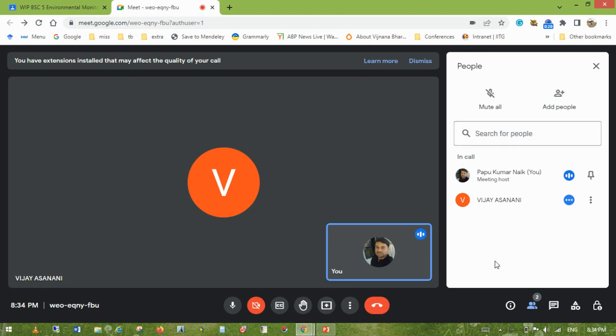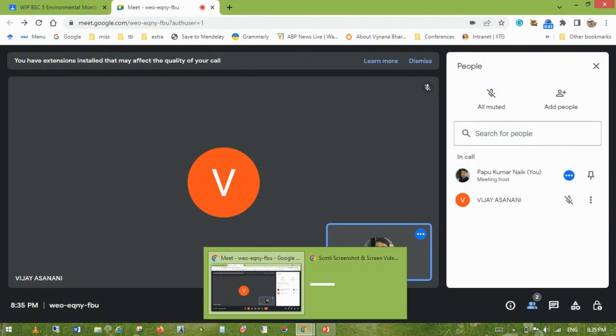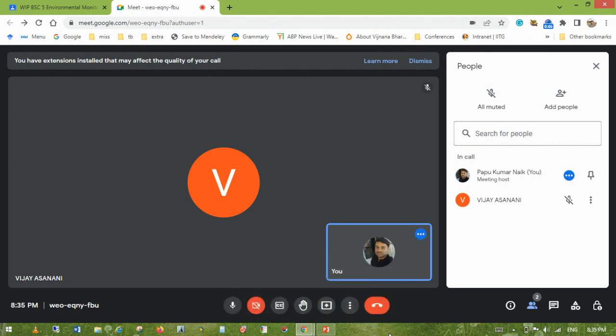So today we will discuss some more about that. Mainly, pollutant contains both particulate matter as well as gaseous pollutants. So first we have to know what the instruments are that can control the particulate matter, particularly dust. The size of the dust, the volume of the pollutant, and the place where the pollutant is generated are the different factors that determine which instrument can be installed, or how much capacity the instrument should have.